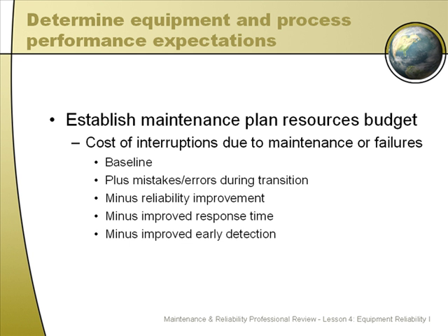As I mentioned before, it's 4 to 9 times cheaper to do planned work. Well, along with that is an increase in speed. One thing that I've seen happen over a period of time, when we've gone from reactive to proactive maintenance in an operation, is the amount of time it takes to execute a job drops by about 75%. I've measured this both in mechanical and electrical and instrumentation type work, and it seems to hold fairly close. If it was an 8-hour job in reactive mode, it'll run about 2 to 2.5 hours of actual wrench time work after you become proactive. It just works out that way for some reason.